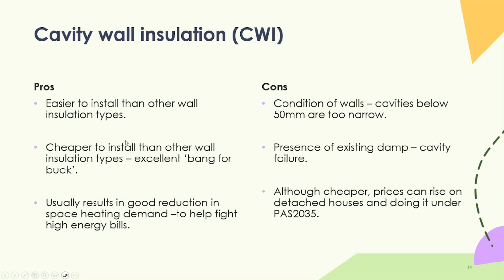Easy to install, cheaper than other insulation, and gives you a better bang for the buck in that sense. You can obviously only do it where you've got the opportunity, a decent cavity, and there are no other issues in there. It's a pretty straightforward job, so usually results in good reduction of space heating demand and associated reduction of energy bills.